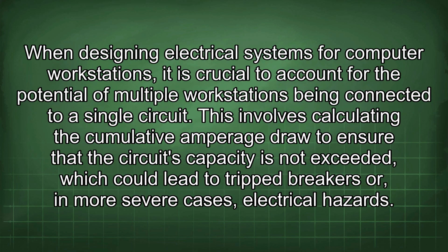When designing electrical systems for computer workstations, it is crucial to account for the potential of multiple workstations being connected to a single circuit. This involves calculating the cumulative amperage draw to ensure that the circuit's capacity is not exceeded, which could lead to tripped breakers or, in more severe cases, electrical hazards.